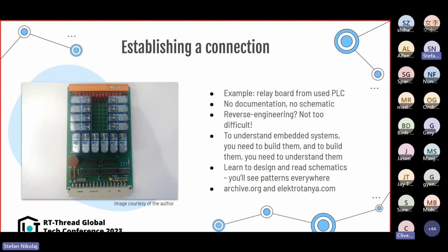For example, this relay board has two series RC filter networks for the relay enable signal. This design choice ensures that stray signals don't accidentally activate the relay board during startup, and only a strong signal from the microprocessor can turn it on. Understanding this choice can only come with experience.